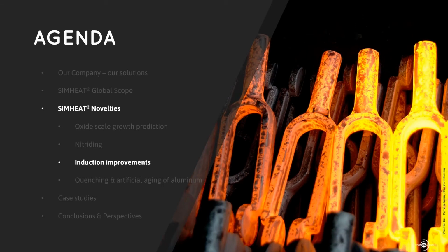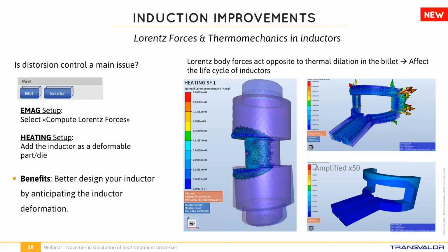Next novelty concerns induction. A key aspect in the design of your production line is the life cycle of the inductors, which will suffer from mechanical and thermal fatigue. Until today, the inductor was considered as a rigid body. By modeling the inductor as deformable, we can predict more efficiently the temperature evolution and the heat affected zone.